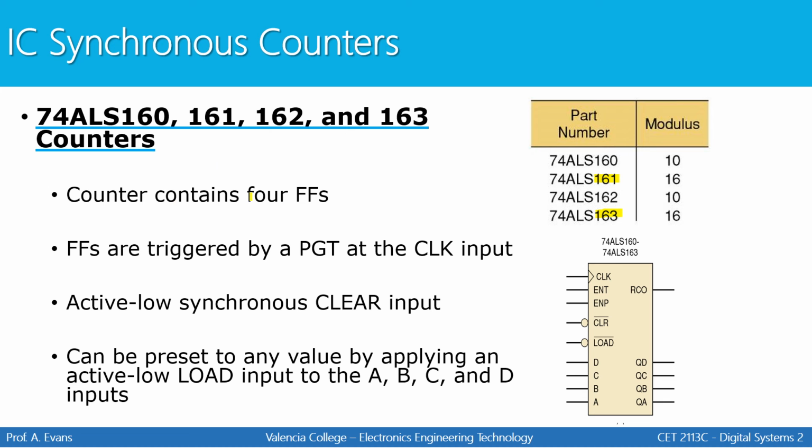Each counter contains 4 flip-flops. The flip-flops are triggered by a positive going transition because there's no bubble on the clock input. They have an active low, synchronous clear input, and can be preset to any value by applying an active low load input, which is right here. Notice the bubble in the bar tells you it's active low.